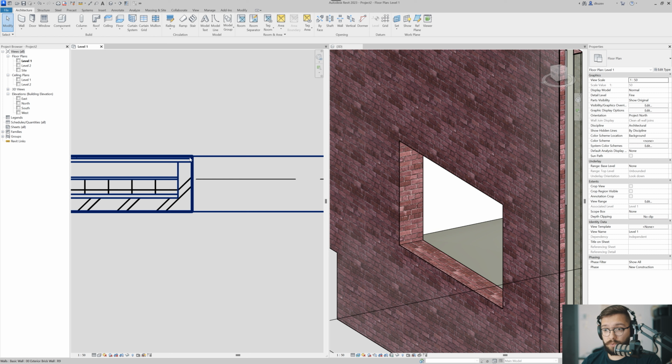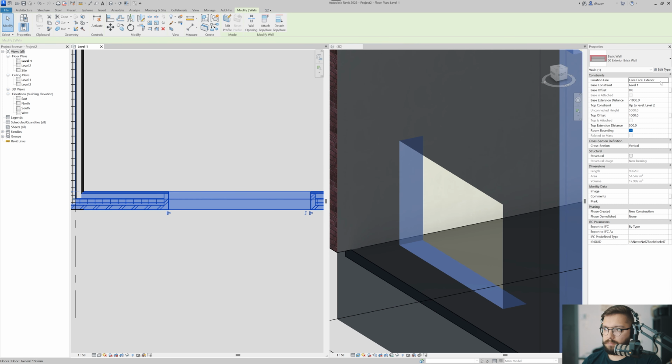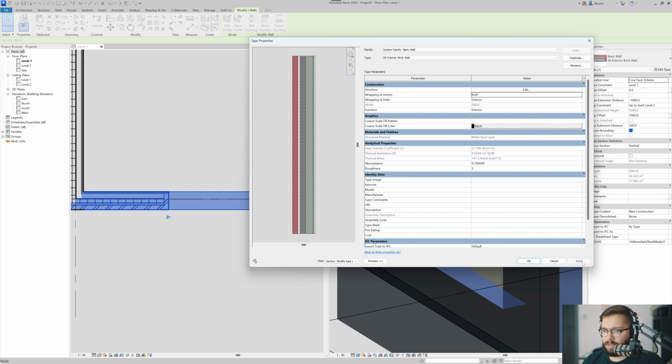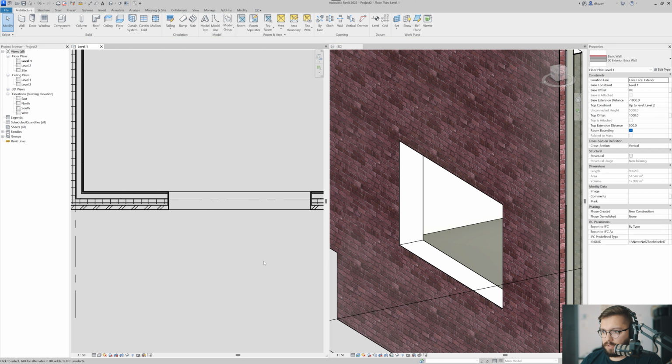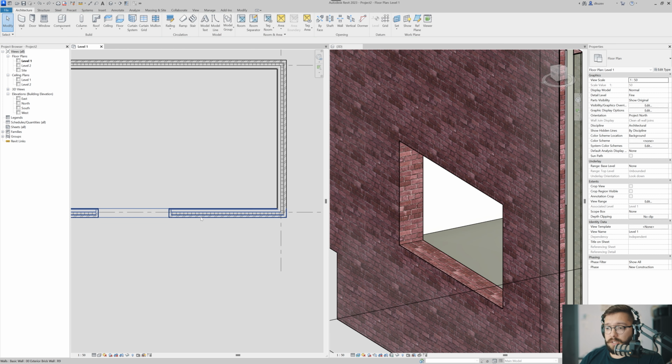Okay, great, but we're still missing, maybe the inside can do it as well. Select it, edit type. And then instead of exterior, let me see if I do both, what would it give me? Yeah, because sometimes it considers openings as an end, which is kind of nuts, but whatever. So let's say if I do interior, you would see that in this case it is the gypsum wall board which is going to do it. All right. So this is your wrapping.